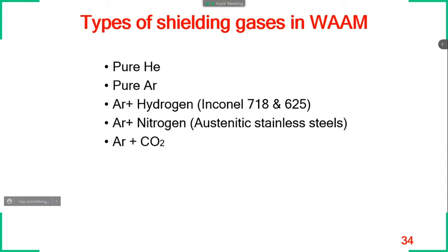For example, I am going to fabricate a material like P91 stainless steel. P91 is one of the boiler grade steels. Boiler grade means high temperature creep is the main concern. If we have a coarser grain structure, that is very beneficial for high temperature creep applications; finer grains are not generally preferred for high temperature creep. So if we want to withstand that high temperature application, the grain boundary should be very stable.